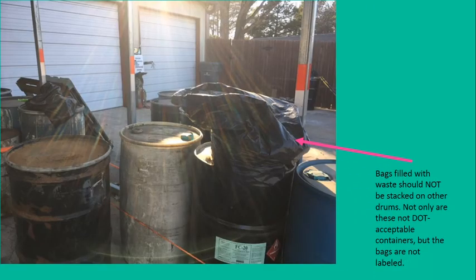So this is an example of when people just drop bags of waste. They may say, oh, it's late, it's absorbent, I'm tired. Okay, well, tough, you need to put it in a drum, and you need to label it. It's not cool just to drop bags like that and expect someone else to figure it out later. Not only are these not DOT acceptable containers, but bags aren't labeled. There's no way for anyone to know what's in there. So, take the extra 10 minutes, drag the drum out, put a label on it.